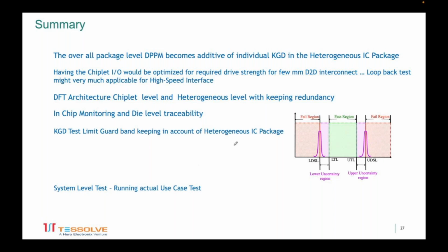Yeah, so generally the system level test is done at a fully packaged level, but what I'm pointing out is this needs to be looked at, if the chiplet itself is to be tested from the system level perspective. At least when you sell a packaged device to the end customer, the fully packaged 2.5D or 3D packaged device definitely needs to be considered for system level test. And again, that will definitely be a socketed test.